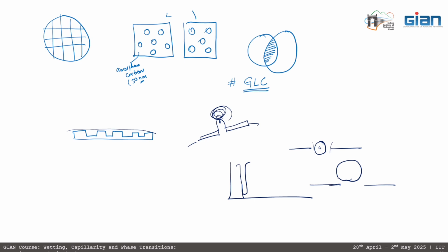If you want to explore more about this field, I would suggest some papers to you. Have a look at those papers, because for this nanopore work the literature is very limited. It was first taken up by some group in Israel, and then a group in Tokyo was working on it. But this is a very powerful method to observe vapor, because vapor is difficult. Gas we can observe using AFM or TEM, but vapor bubbles are the difficulty. Also, the probability of homogeneous nucleation for a vapor nanobubble is very low, but in such confinements we observe homogeneous nucleation.